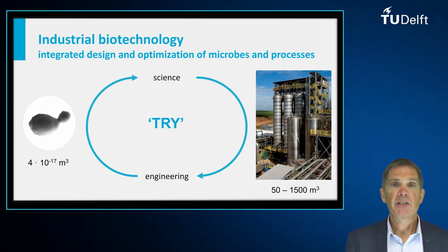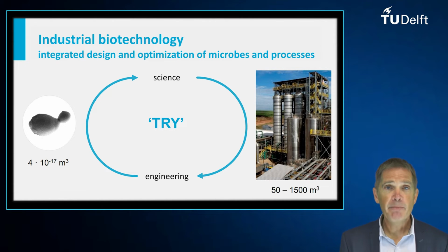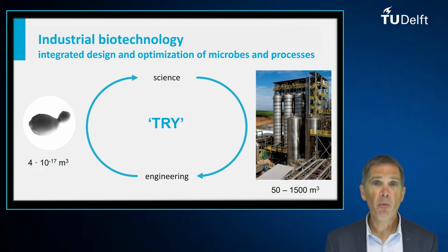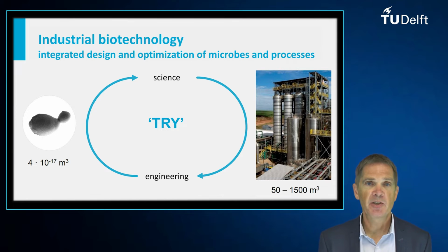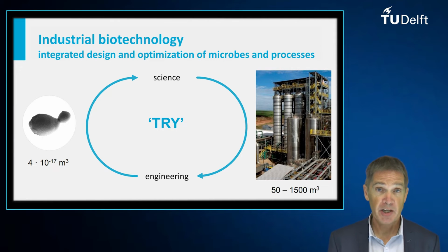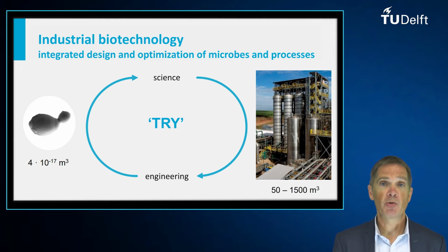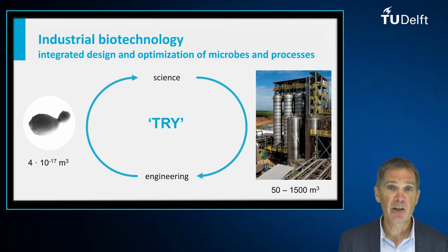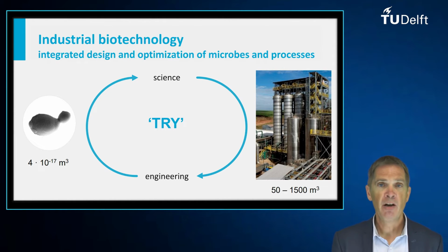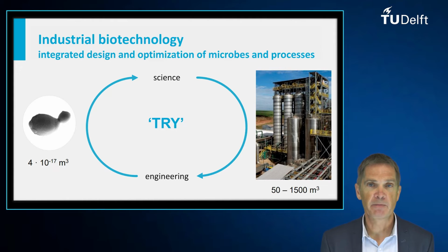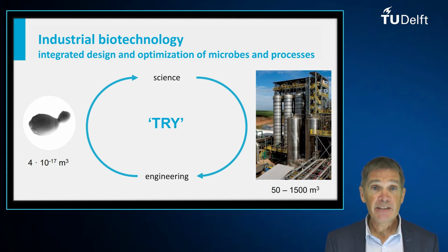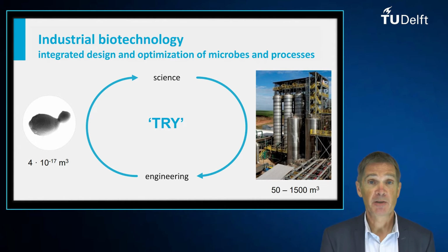The answer to this question is twofold. For any microbial cell factory, we have to optimize the conditions in industrial bioreactors, for example, by tuning the temperature, the pH and the oxygen concentration to achieve the economically best combination of titer, rate and yield. Secondly, we very often need to improve the performance of the microorganism in the full realization that this may change optimal process conditions.